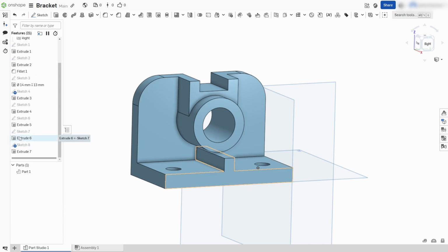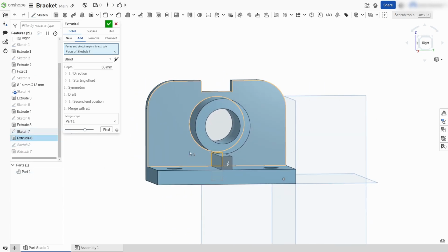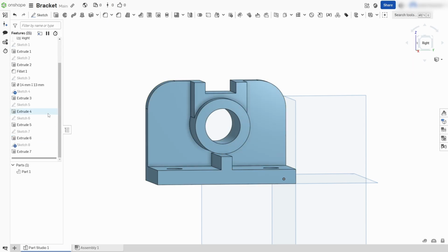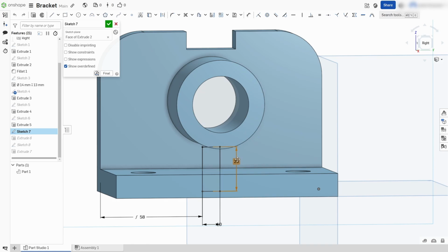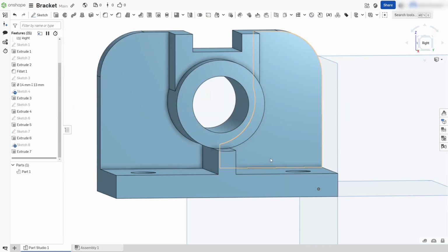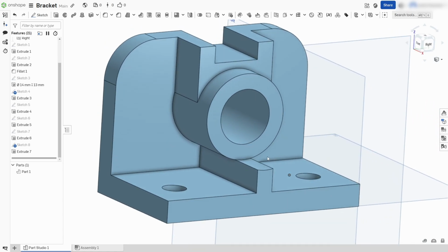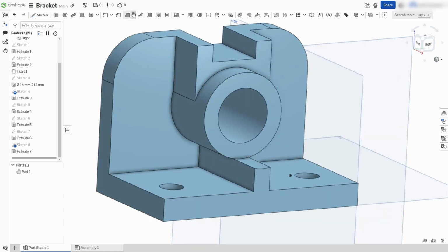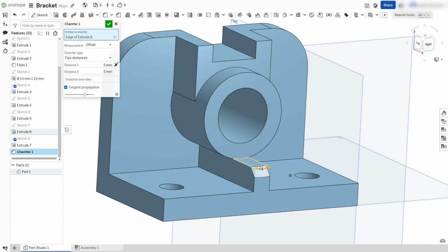Okay, and then we will re-extrude that surface right there, so we can redo that sketch, and we will raise up this 25, and now maybe 35. So we're showing something was broken, and this is the way to fix it. So now we're going to add that chamfer again. So here we go, chamfer to this edge.